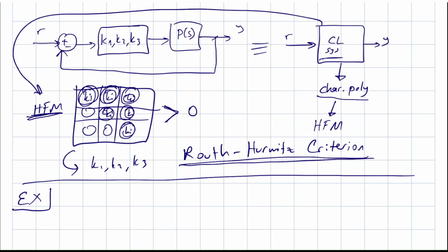However, it will not be an LMI, but not all hope is lost. It will be a BMI, which is not body mass index, but bilinear matrix inequality. And there is some hope that by using PENBMI or BMIBNB type of optimization solvers, using MATLAB and YALMIP and those BMI solvers, we can again determine and compute those ki, our control parameters.